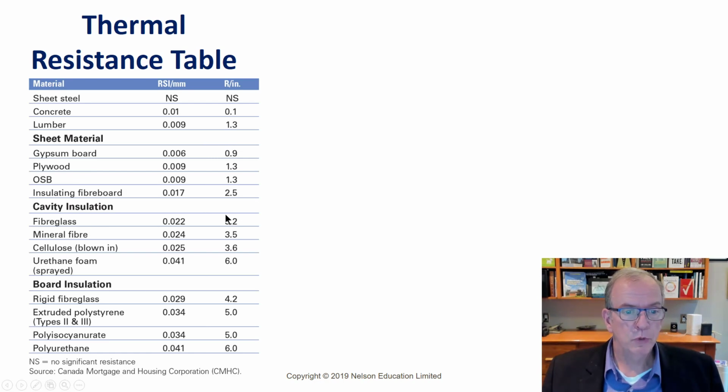Fiberglass is 3.4. Some of the newer fiberglass that you'll see, like that's listed on the Doncaster drawing, is higher than that. I think it's around 3.9 R value per inch. So to get up to R24 or R22.5, whatever it is, the R value is significantly more, like that's 32 times more than concrete.